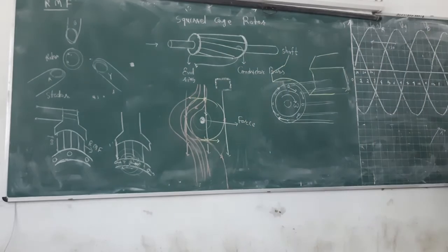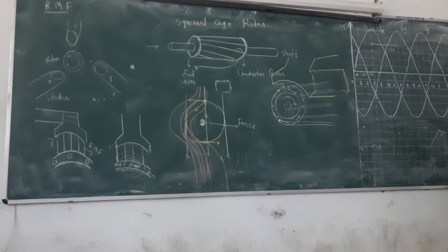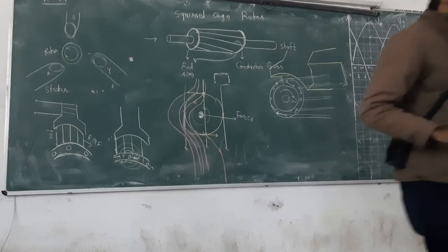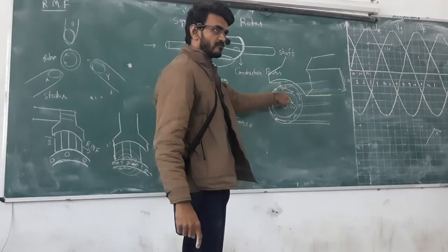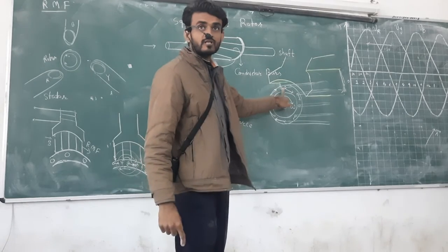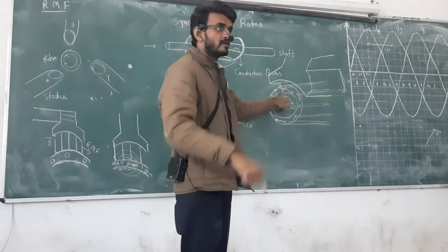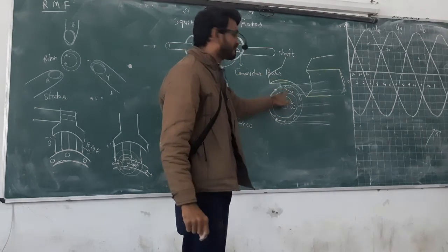Now clear again. If I have a magnet and a conductor, and I move the conductor, the relative velocity is maximum. If I move the magnet and conductor slowly, relative velocity is there, but less. So initially maximum EMF is induced inside the rotor because the relative velocity is high. During rotation, the relative velocity is low, so a small amount of EMF is induced.